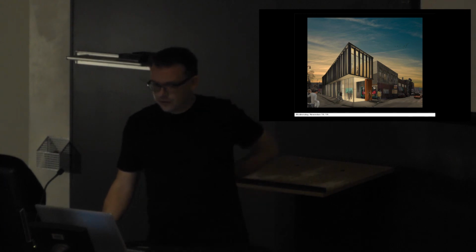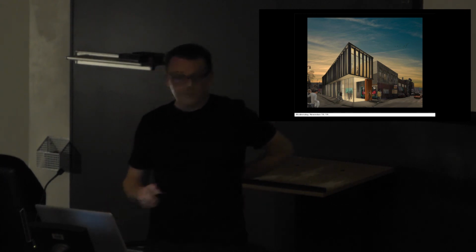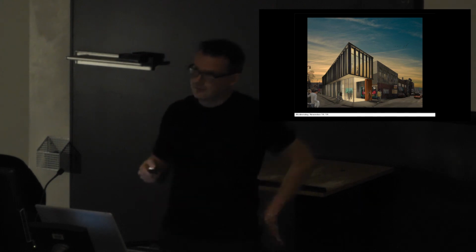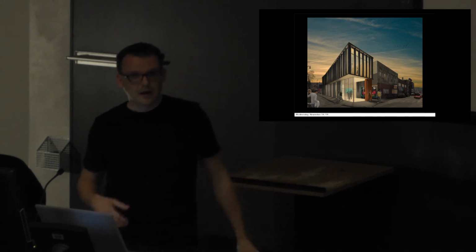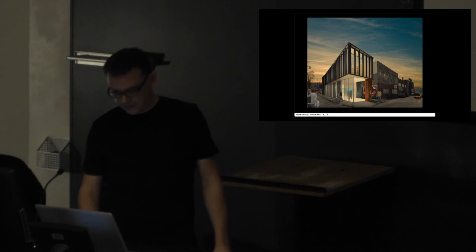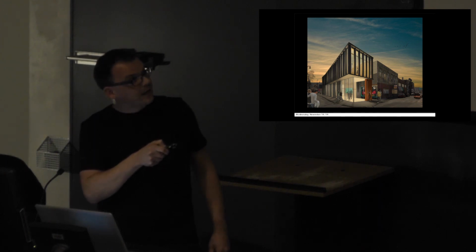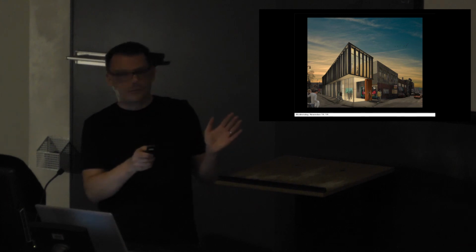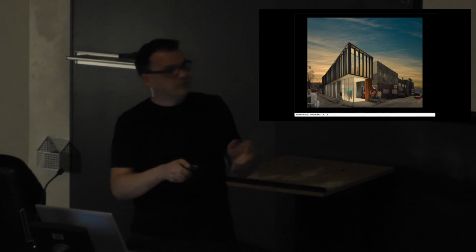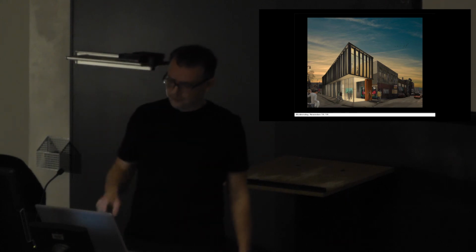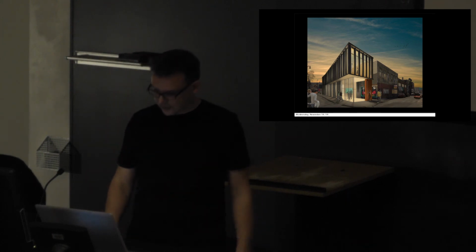The studio is wrapped in a curtain wall with transparent and translucent glazing. We don't really show this here in this rendering, but there's a kind of an interesting rhythm between clear glass and translucent glazing. And then we have these vertical louvers that separate the glass every 35 or 34 inches on center, these louvers occur, so you get an interesting verticality in this otherwise very horizontal building.